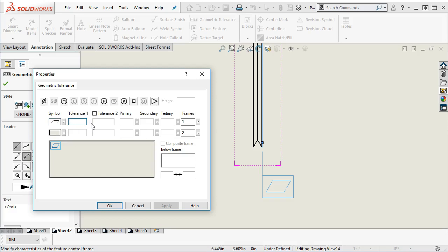And then we have to decide, are we going to be right at, with our plus or minus 5, the 5 thousandths flatness and 5 thousandths parallelism? Well, we're using up an awful lot of tolerance. So I wouldn't really carry it out to 2.5 thousandths. So that's kind of where a standard, you'll see a lot of drawings have 2 thousandths of flatness and 2 thousandths of parallelism. Right? It stays under the 5 thousandths tolerance, but keeps it tight enough that we won't be growing that tolerance zone outside of our standard tolerance that we just applied.